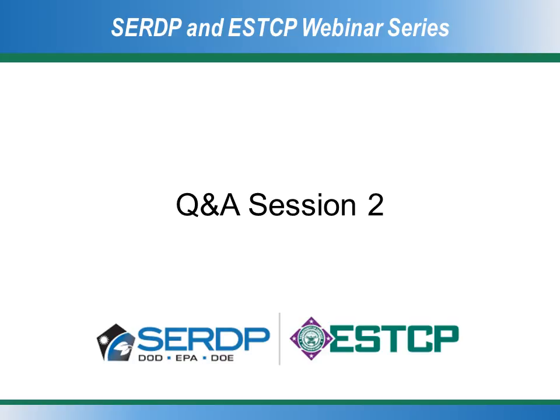Great, thank you. How important is understanding data noise when creating ERT images, and how can field data noise be estimated? So understanding your data noise is actually quite important when producing these images of conductivity or resistivity, because it can have a large effect on what you are actually able to resolve in your image.